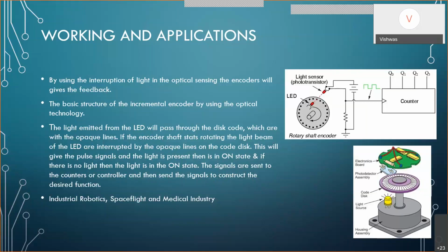It sends out a light signal, and there is a phototransistor right next to it, which looks for the reflected signal. The reflected amplitude changes based on blood flow: for every contraction and relaxation of the heart, the blood flow reduces and increases. Based on this, the heart rate is calculated using the same technology.